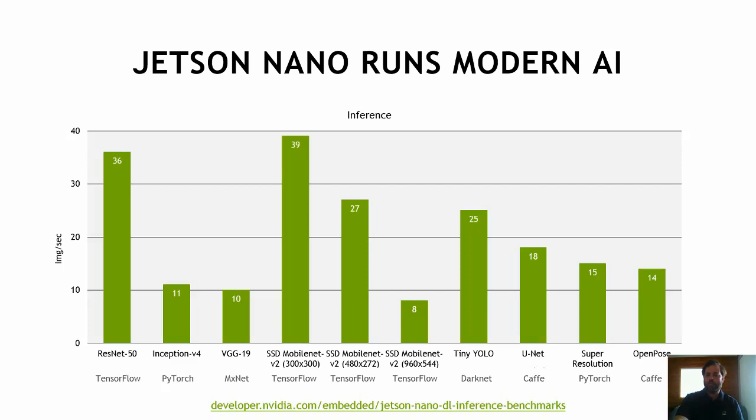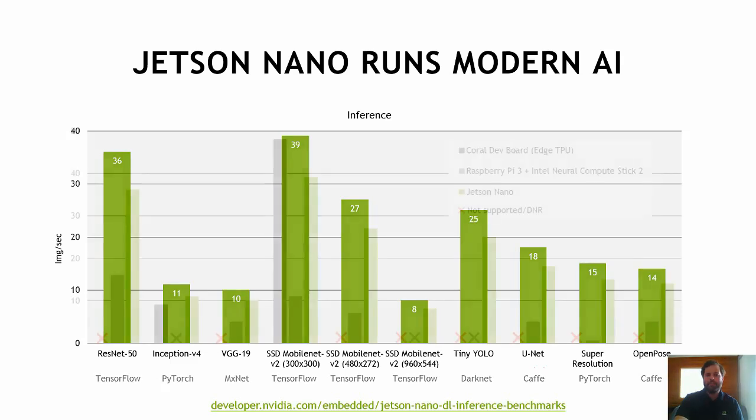OpenPose is what we ran for pose recognition, which extracts the positions and orientations in 3D of human skeletal features of people in a video stream, like the locations of their arms, hands, fingers, face, feet, legs, and bodies. With this info, you can do behavior recognition and gesture recognition, for example, signaling with a robot or implementing collaborative safety features in a factory or warehouse environment.